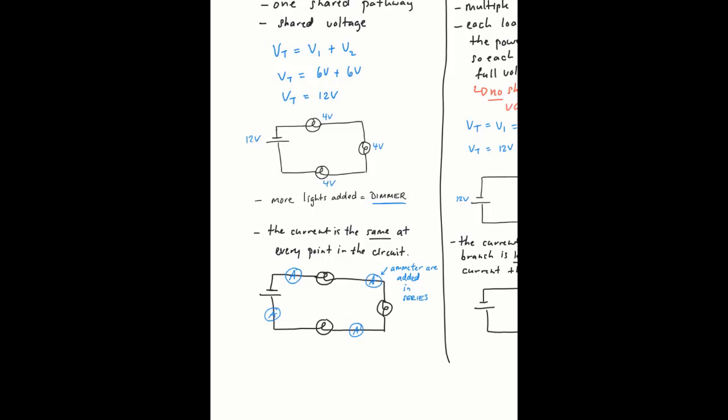What would you see? Well, if we're talking in terms of the numbers that you'd see, let's say that we started off with 3 amps for the value of our battery. Okay, and we knew that because when we used this ammeter, it tested as 3 amps. When we use this ammeter, it tested as 3 amps. Okay. When we tested over here, it was also 3 amps. When we tested over here, it was also 3 amps because it is the same at every point in the circuit if it's a series circuit.